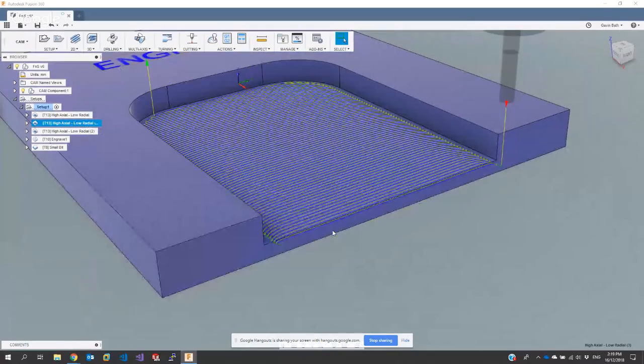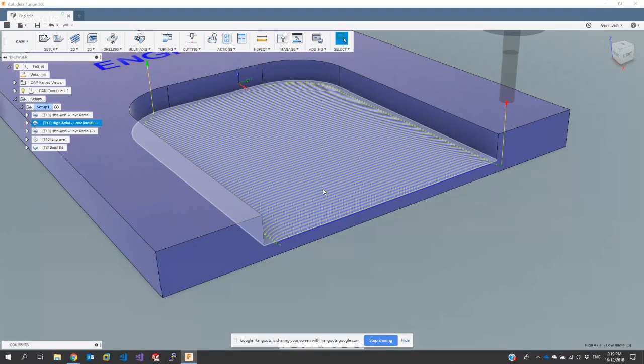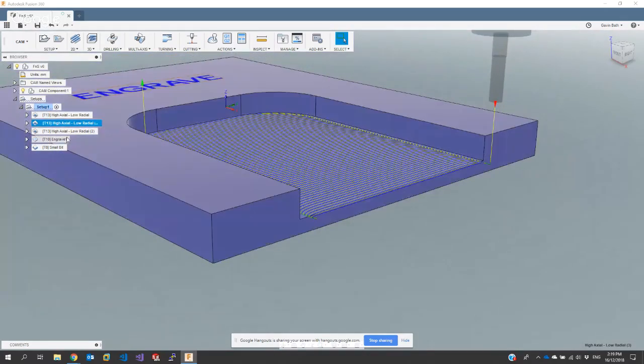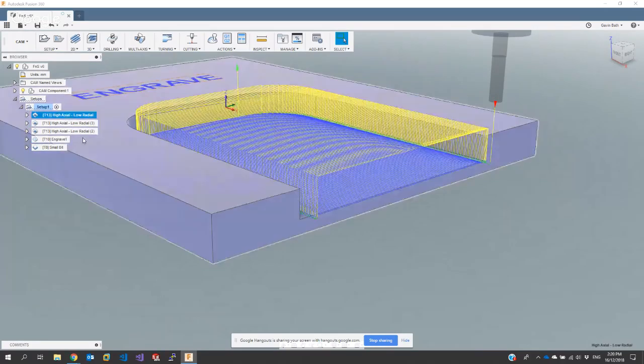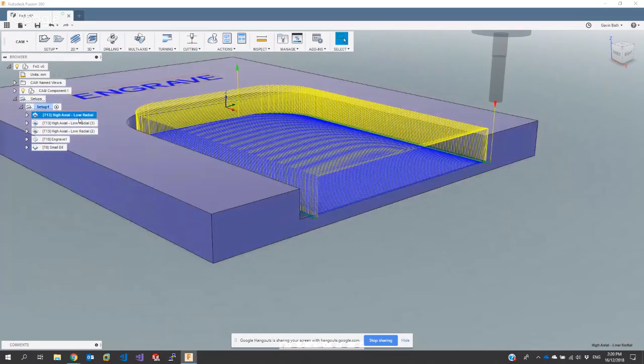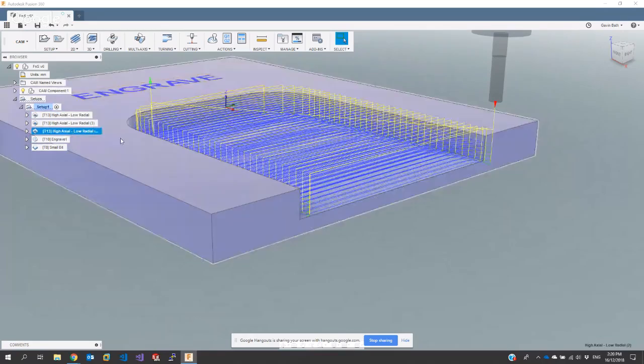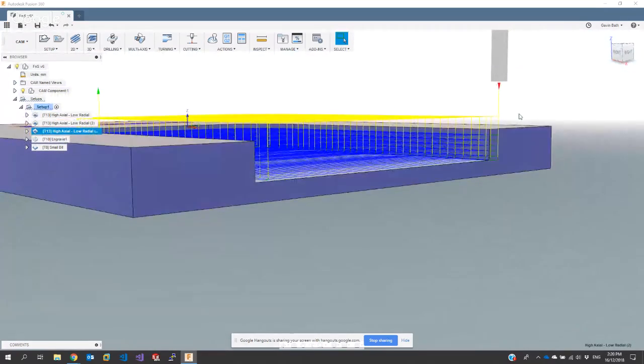So I guess the next thing, when we're trying to come up with numbers for the spindle RPM and the feed rate, as we were talking about at the start, there's no silver bullet. There's no one number that's going to work for everything, of course. It really varies on what you're doing. So when you're setting those feeds and speeds, you also have to think about how you're going to attack the job. I guess the broadest category of difference would be whether you're going to use more of the length of the tool and less of the diameter, or less of the length of the tool and more of the diameter.